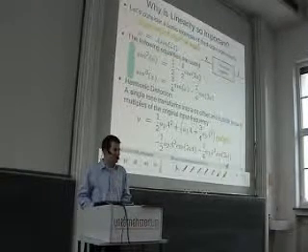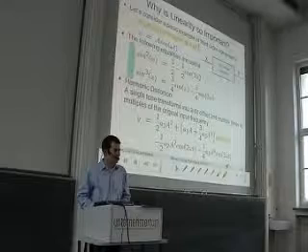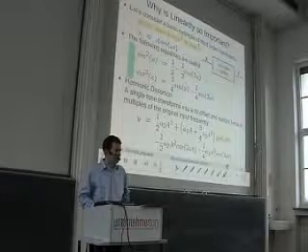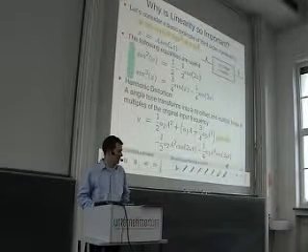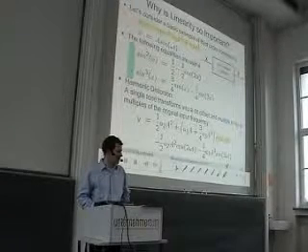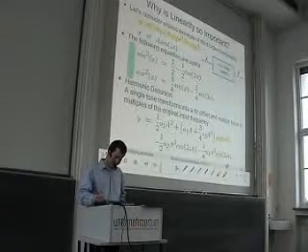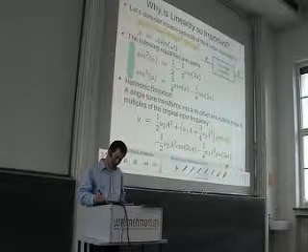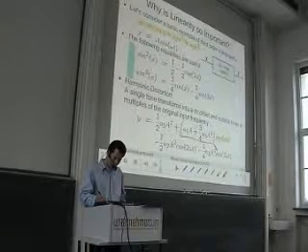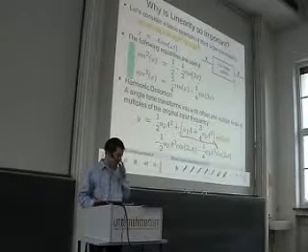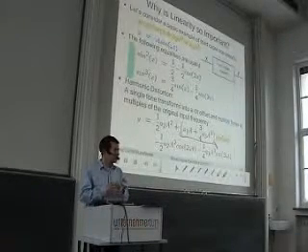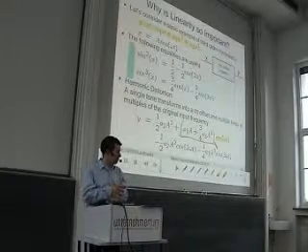You do not agree. Why not? Yes, you consume energy in these harmonics. Yes. This is a good one. You say we also have an impact on the first harmonic, and this is absolutely correct if you look at this term. From a linear system, you would expect that the gain of the system is always the same. It's constant, independent of the amplitude.